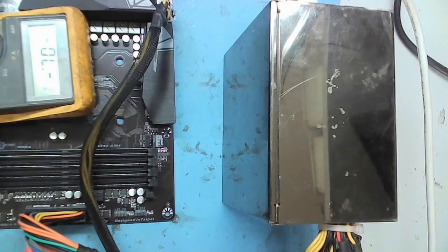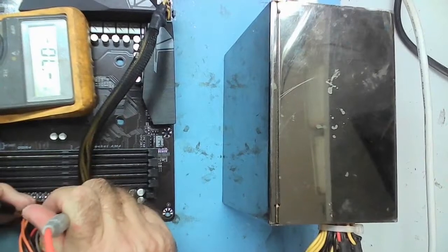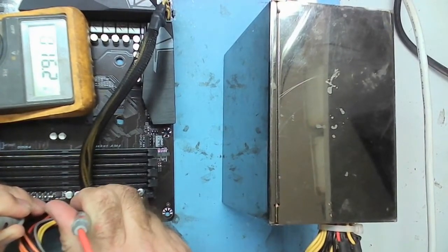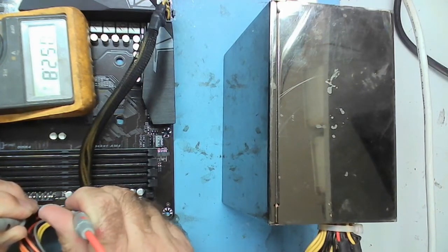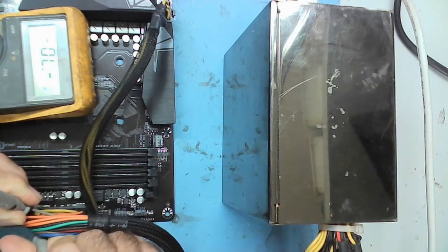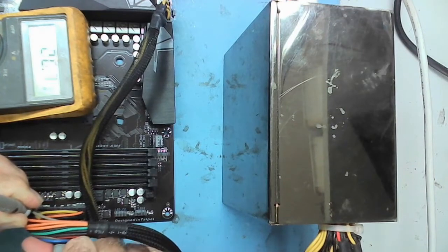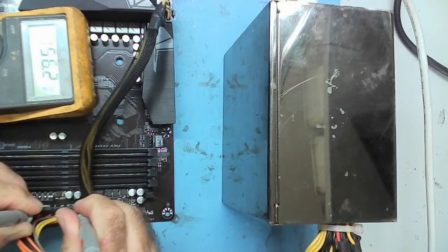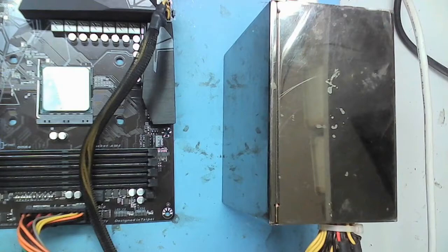So we're going to check now on here. We check from the purple, which is standby, to one of the blacks. No short on the standby. That's really much like the other one on the 3.3. That's good. Reading on the 12, on the green, no shorts on that one. Red. Yeah, especially that one reads about 20, the other one was slightly lower, but that looks reasonable.